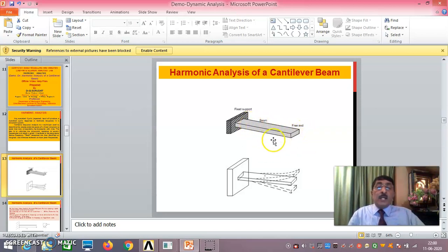That is why finally in this harmonic analysis we draw a graph. On y-axis it will be the amplitude of vibration. On x-axis it will be the frequency. Let us say 0 to 100 hertz. Now 0, 1, 2, 3, nothing. Amplitude of vibration on y-axis will be minimum. Once you come to 8.2, first natural frequency, it picks up. The amplitude of vibration will be very much more. It is dangerous. Then again 9, 10 and all that, it will be again minimum.